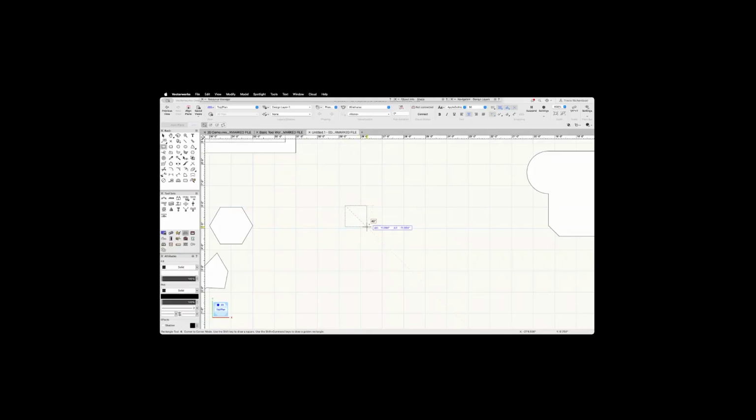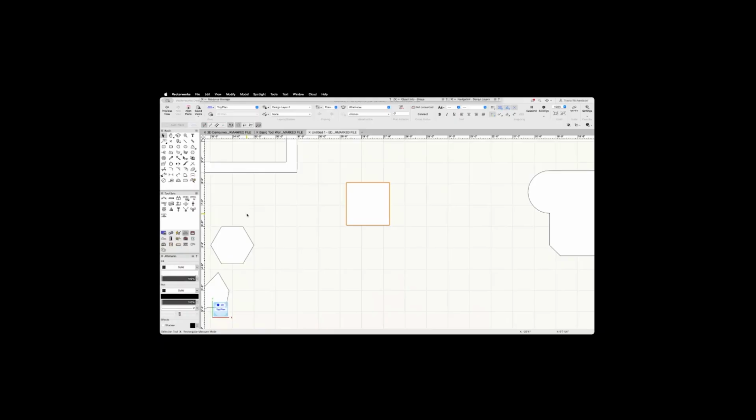Yep, that looks a little bit better. And I'm going to make that 2 feet and make that 2 feet. Great. And I'll click to complete. There's my new rectangle, the size that I want it to be. And then with that selected, I'm going to select my offset tool. If I were to click outside of this box, it could create a box that is 1 inch larger all around. This one is actually on top of the original rectangle that I drew.